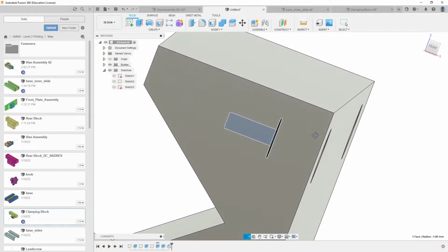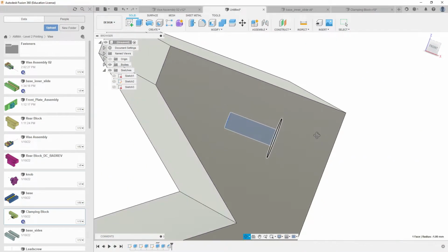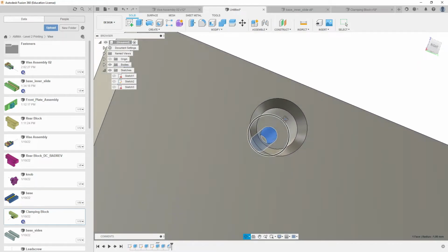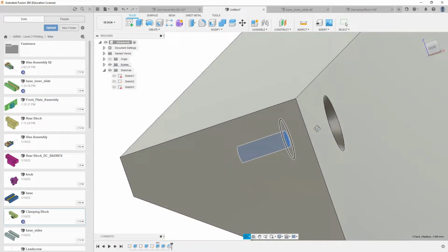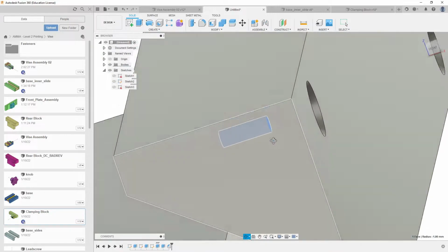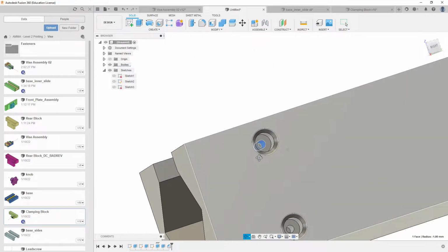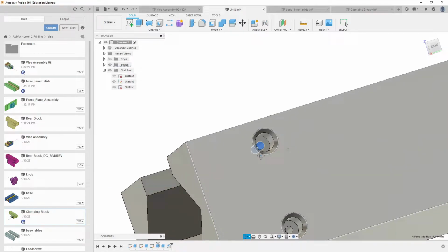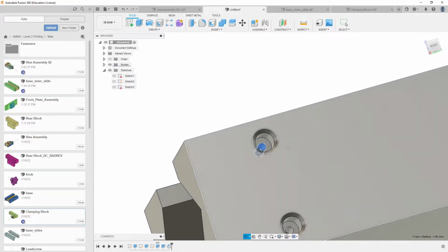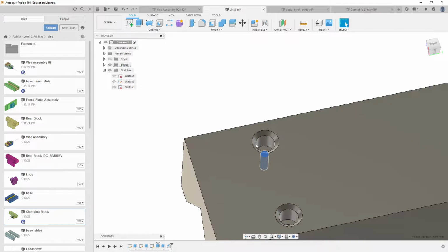So that gives us still 5 millimeters. How deep did I just make that thing? 6. So it'll give us enough to tap into if we want, if that works. But if that does not work, then we have a hole here for our heat set insert. We might even try the heat set insert first, and if that doesn't work, then we can fall back to the holes. So we've got either or.